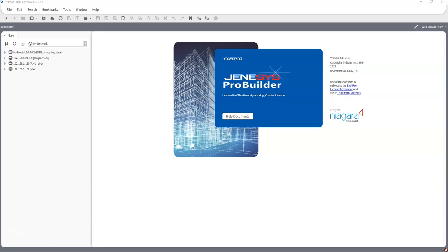And when the zone commissioning cycle is complete, each zone VAV commissioning report is then combined into a single zone commissioning report. So the continuous commissioning features of the VAV system provide customers with the means to ensure ready operation of a critical air quality and control system. Its configuration has been simplified so that the implementation pretty much requires minimal effort.